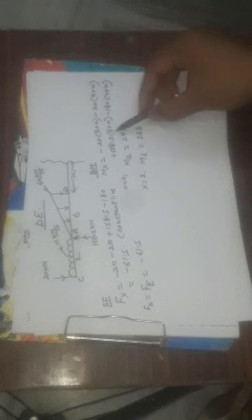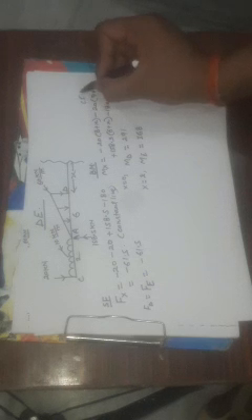Put the value of x into this equation, we'll find the value 168. Variation: shear force here is a constant line. Obviously, the power of x here is 1, so the bending moment variation will be an inclined line, or linear one. Right?